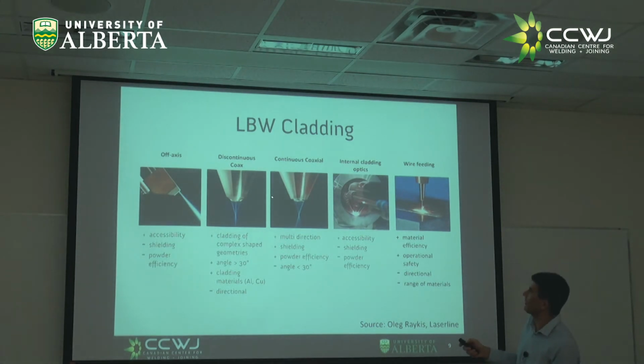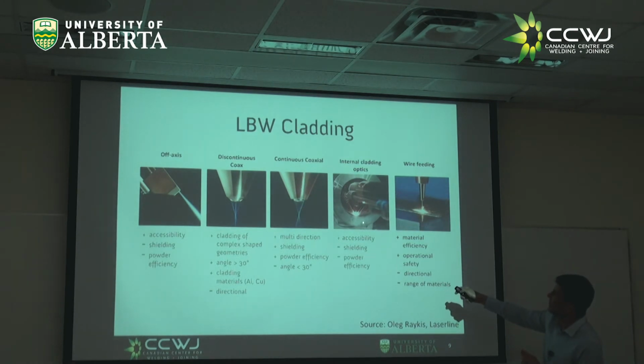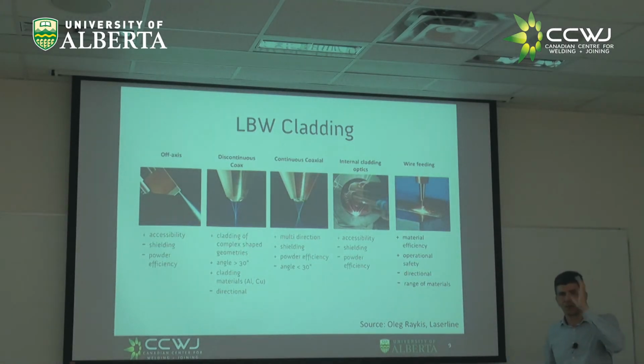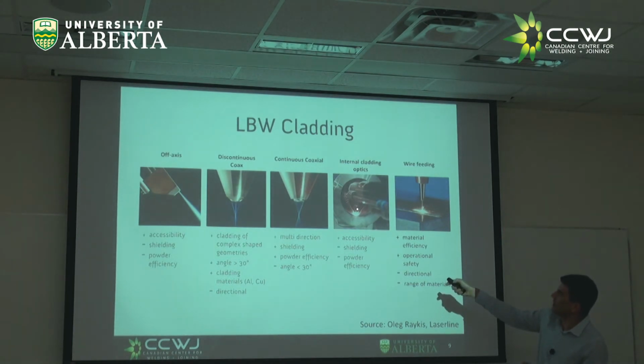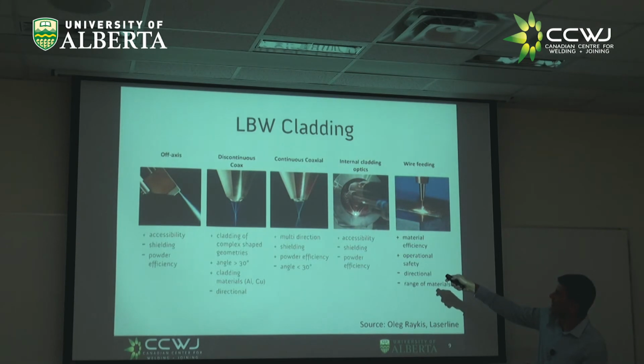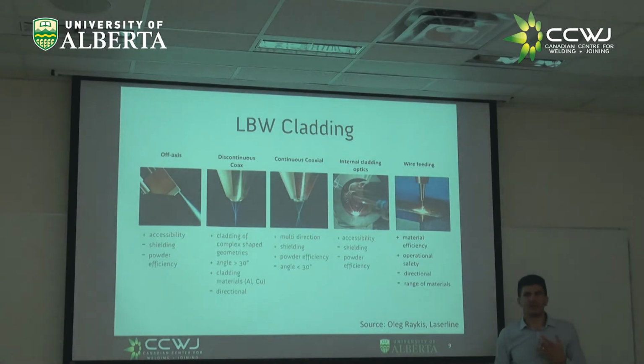In our lab, we have heads for all these. They're not mounted yet. Internal cladding optics, right? You see here you have a small borehole, and you're coming in with a tool, and this tool sometimes has an optic. It has optics at the end, and projects the light here inside. Now, this is tricky. You can imagine how hot it gets right there. And you want to put powders, and it's hot.